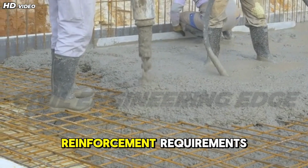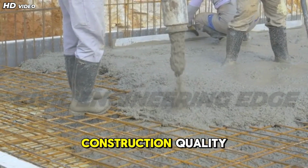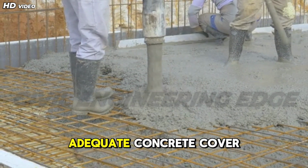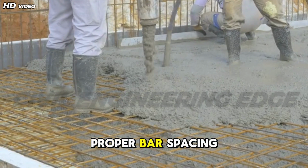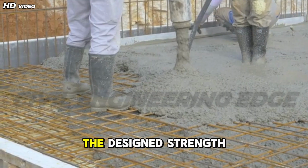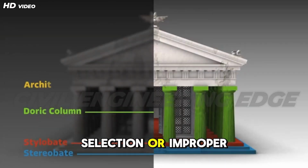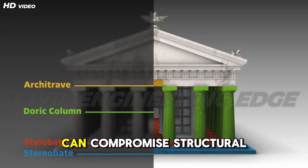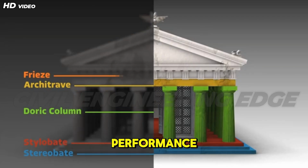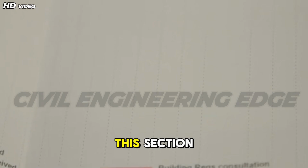Concrete and reinforcement requirements also directly affect construction quality. Adequate concrete cover, proper bar spacing, and good compaction are necessary to achieve the designed strength. Poor material selection or improper detailing can compromise structural performance, even if calculations are correct.